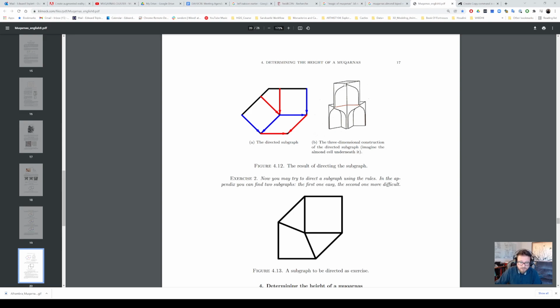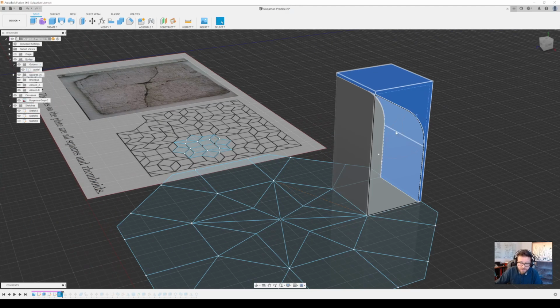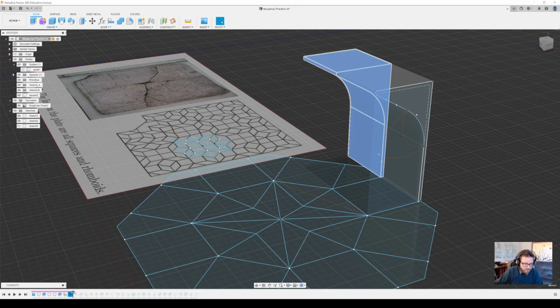So that's like from here to here. So the arrows are always pointed in the direction where the curve is going and where the object is moving up. Okay, so it's here to here and here to here, etc. Okay, so I need this and this to match. So going back to Fusion quickly, all I have to do is do this once, and it's a simple rotation. So what I'm going to do is make a copy of that object and get rid of my guide. You can see I've made a copy paste, and then I've moved it, okay, down to the edge.